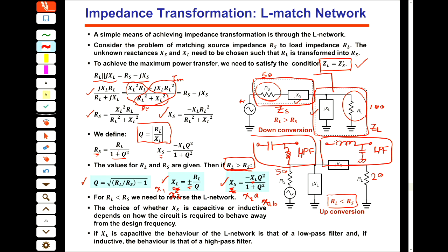The behavior of this is a kind of high pass. In low frequency, with that L and that C, you do not let the signal go through at DC. But when it is CLC, then at DC all the signal passes through. So in low frequency it is good, and then at your frequency it goes high and then goes down. So the behavior is different. But at operating frequency and the bandwidths that you have, it works similarly.